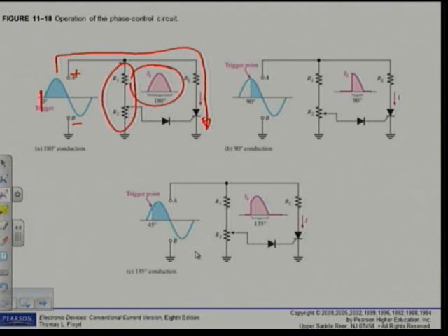That means I got now maximum power in this circuit, because the negative cycle, that means this is the negative cycle. What will happen, then it will become negative there and positive there. The SCR will be reverse biased. When it's reverse biased, we won't be able to get any conduction. That is the A one.